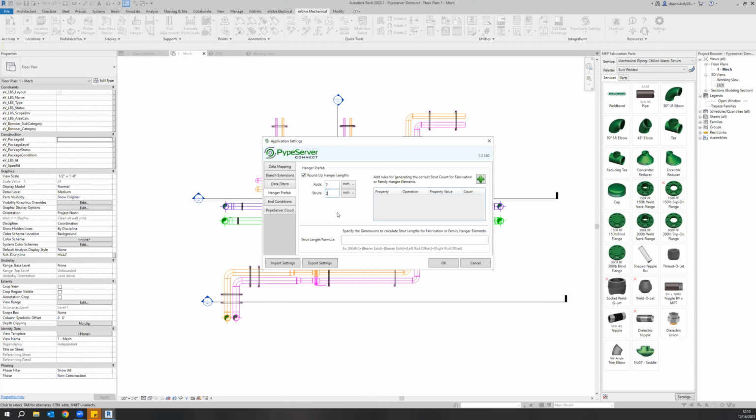On the right, this is a way that you can account for sandwich type hangers where you'd have multiple struts. So you would add a row here, give it something to look for, and say my sandwich strut hanger uses this terminology. And what that terminology means is that there are 2 or 3 strut hung on the same hanger rods.